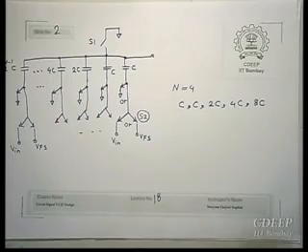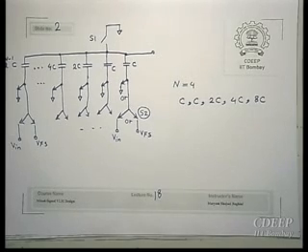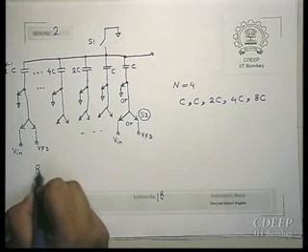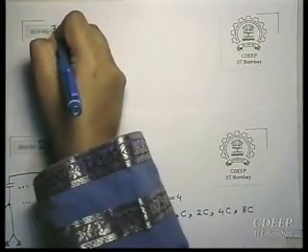This is quite straightforward. The next step is to sample V in on the capacitors, because before doing any comparison we need to sample V in. So the first phase will be reset. This is obvious.